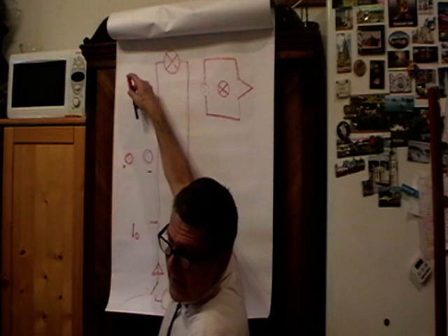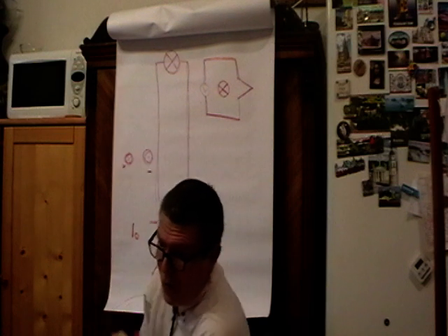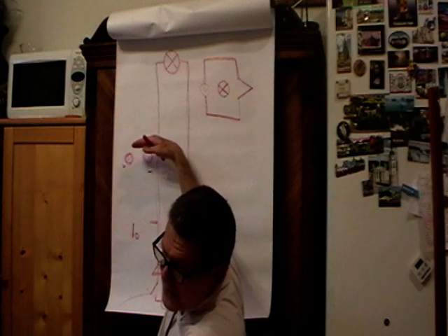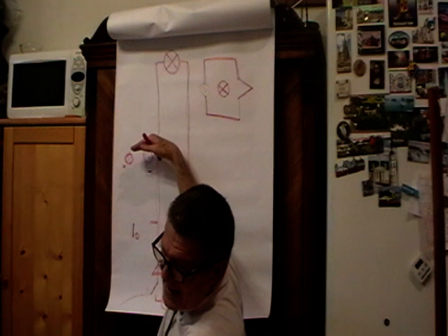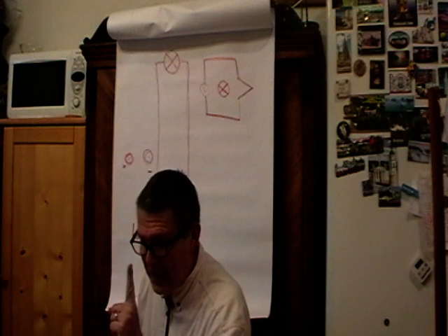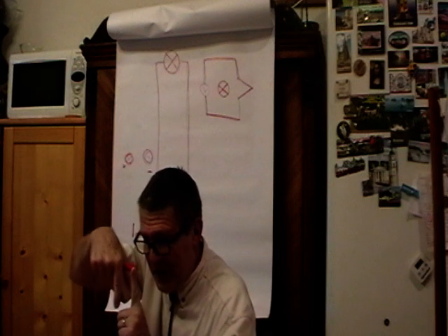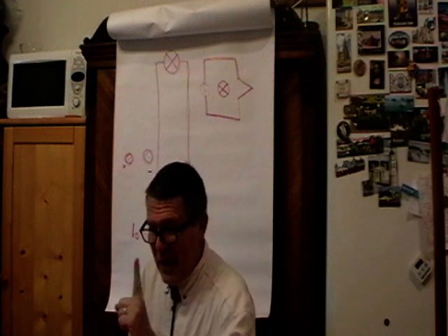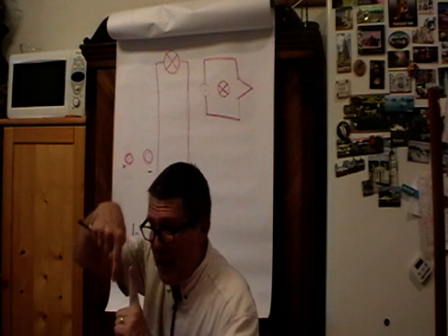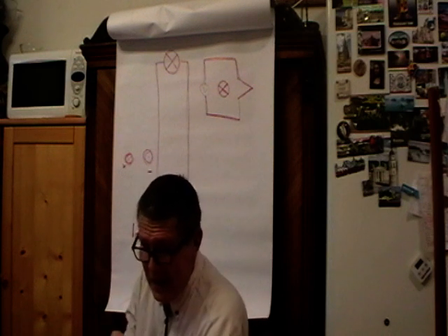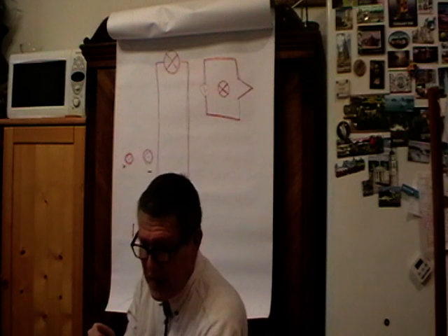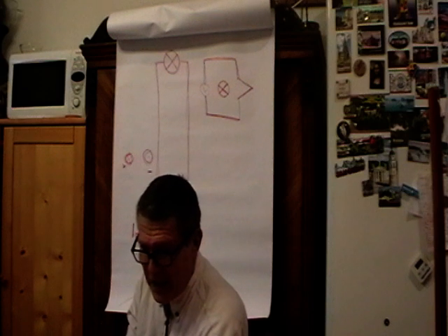It reflects antiphase voltage, in-phase current, which means that at the place where both waves are present, there would be a strange situation. We have one wave with voltage plus V and one wave with voltage minus V, which is zero voltage. And we have one wave with current I0, and one opposite wave with the same current I0, which makes two I0s at the points where both waves have already reached.